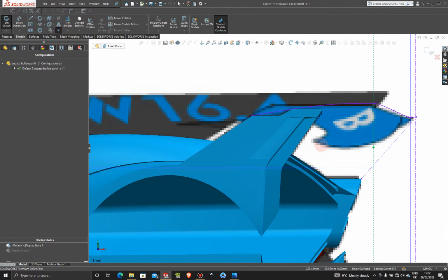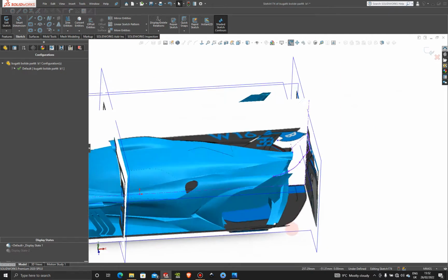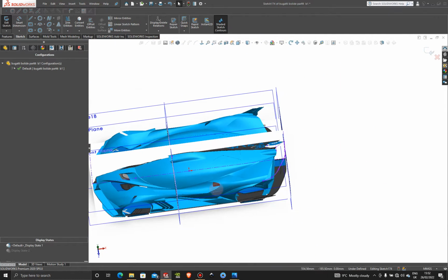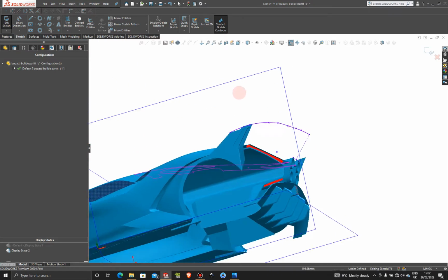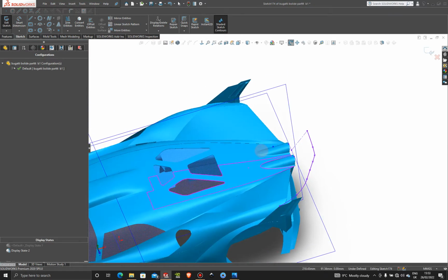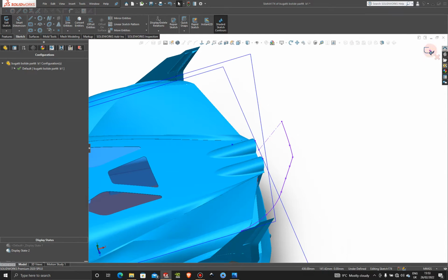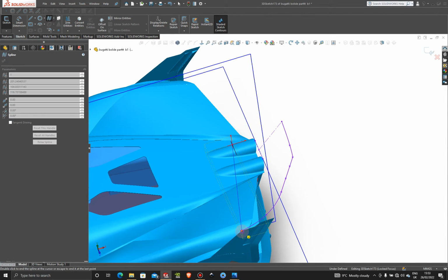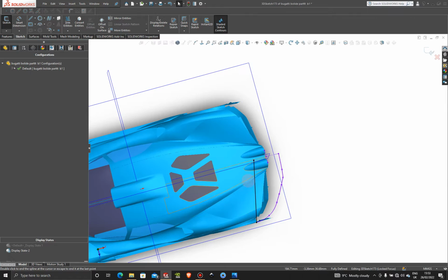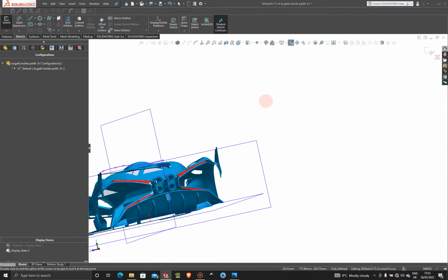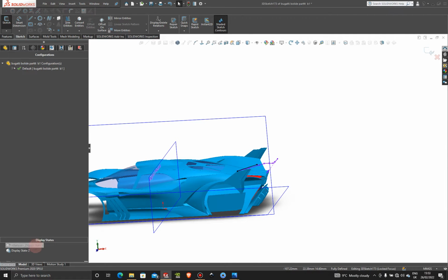And we're gonna grab a point and drop that point somewhere here. Okay. And if we jump into our second display state, you can see that point falls right where we want it to be. So let's exit the sketch. And let's jump into a 3D sketch through this spline, and we're gonna go from this point to this point here. So we're not going to make any adjustment to this line from the top, but only from the back.